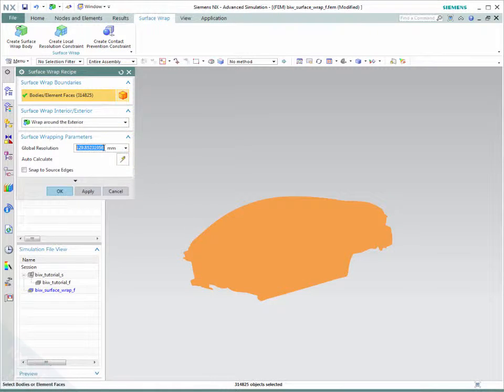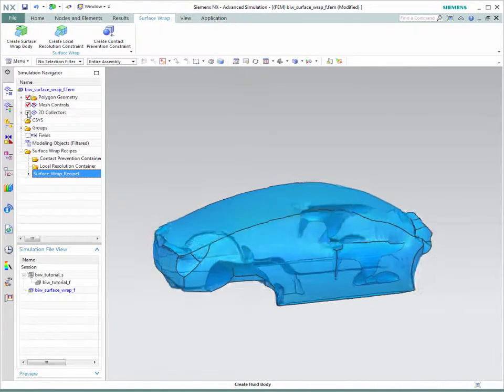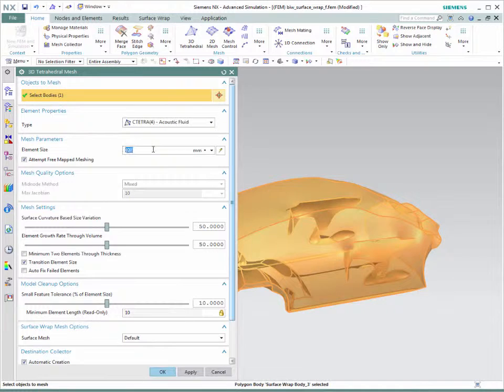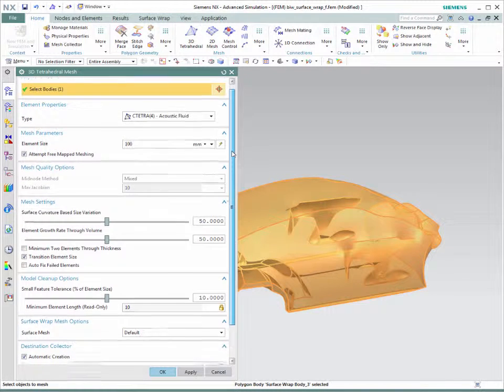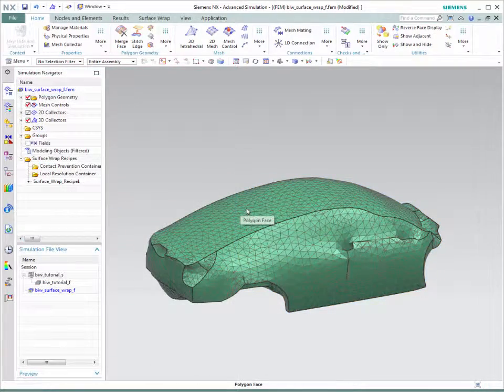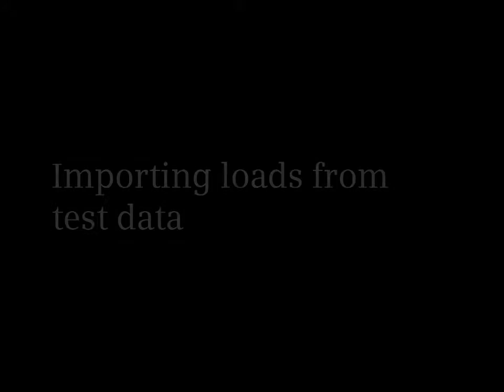And so you can just start off with, say, an STL mesh, an orphan mesh with no underlying geometry, and you can create the internal fluidic cavity out of there, just as you would with regular geometries. And this would let us move into domains beyond CFD, like acoustics, for instance, where these kinds of rapid creation of fluid domain will be highly beneficial.